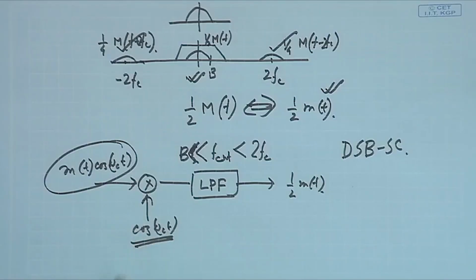Why am I saying all these things? This will give me another design direction, where I will take out this difficulty of the carrier recovery circuit and then multiplying. So, this entire stuff I will take out, and I will employ another modulation scheme which is just a simplified modified version of this, where the receiver becomes very simple, but the transmitter is a little more complicated. We will show you what kind of complications you will have in the transmitter. Probably the transmitter will be a little less efficient, but that is pretty obvious.